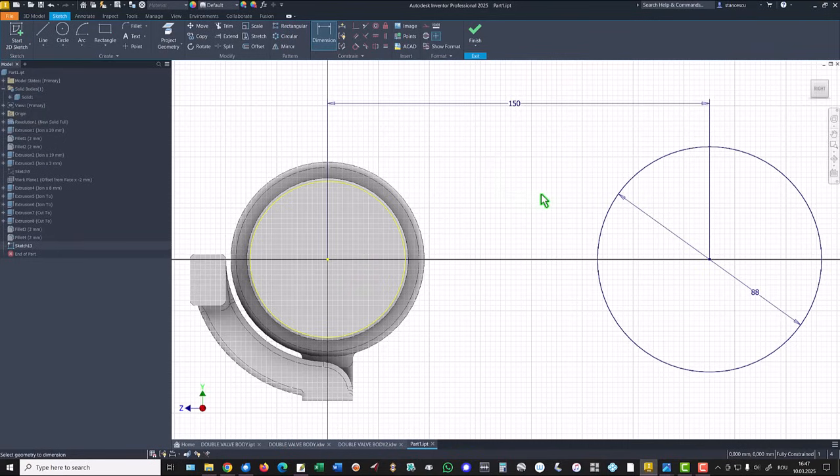You have to remember this. We start from this point, we draw a horizontal, we press the left button of the mouse, we go here and we find the tangent, then we add tangency here.